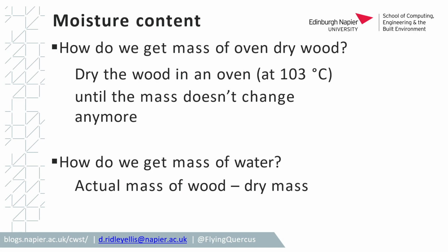How do we get the mass of the oven-dry sample? You chuck it in the oven at 103 degrees Celsius. What was our oven set at? Was it 105? Who cares. 24 hours, job done. For samples this sort of size, 24 hours is absolutely fine. Bigger samples have to go on for longer. In actual fact, I put some dowels into our oven down at Seven Hills last week, and they had been in there for a full week. It makes no difference to them. They're not going to go on fire.